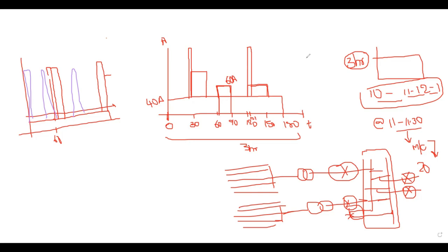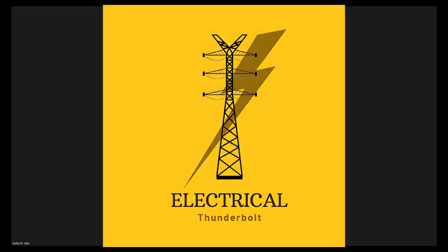Again, if I am placing 112 cells, during the low voltage discharge, like minus 10% of the 220 volts, which is 190 volts, then the battery may get discharged and each of the cells could come to like 1.85. So that is the end cell voltage where we have to again check some condition. Let me show that in a practical way, then you can understand the concept behind this. So let's wait for a minute. I just want to bring this up.